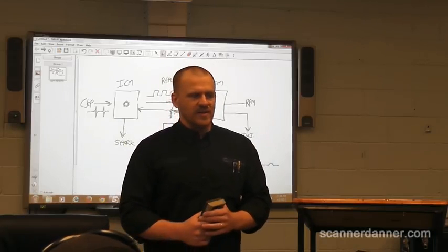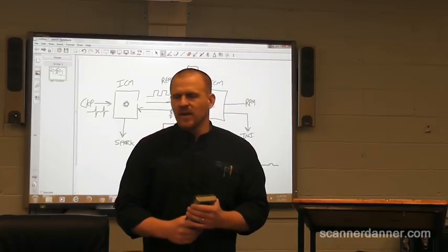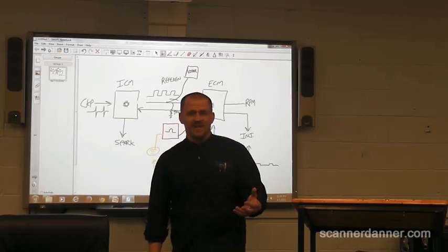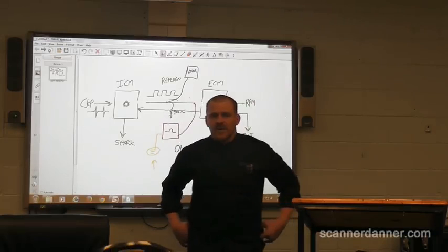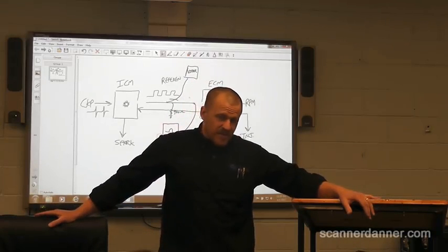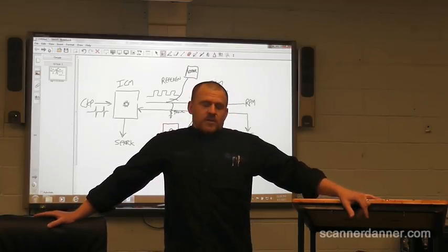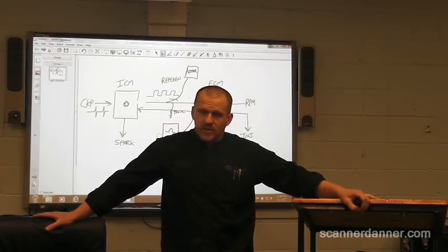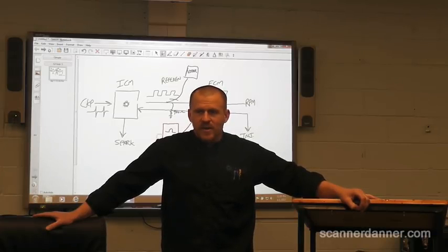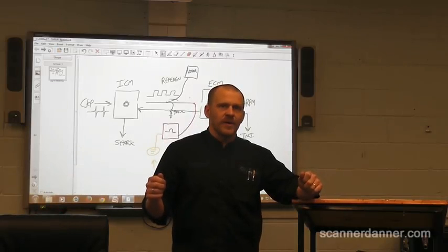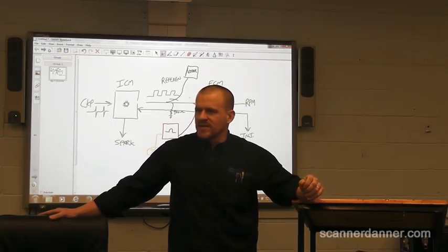If you're doing short to ground testing, what page is that? 23. If you're doing short to ground testing, make sure you're on your highest scale if you're using a non-auto ranging meter, or if you change your meter from auto range. There's another issue here, guys. On the highest ohm scale, if you touch your leads, the meter will travel the electrons through your arms and you'll get a reading. If you go end to end with your leads, you'll have around 200 to 400,000 ohms of resistance on average.